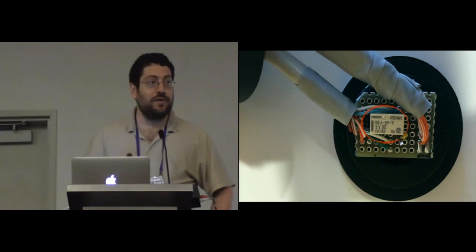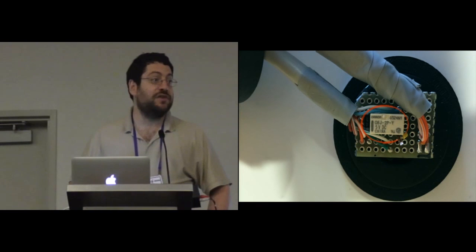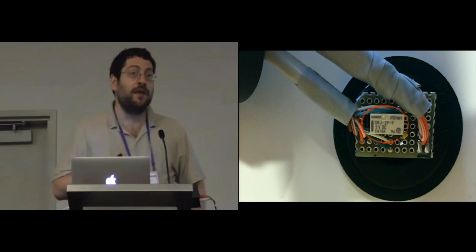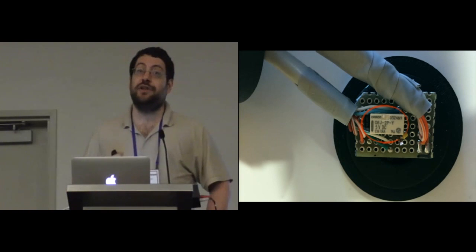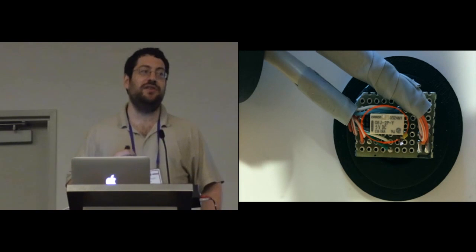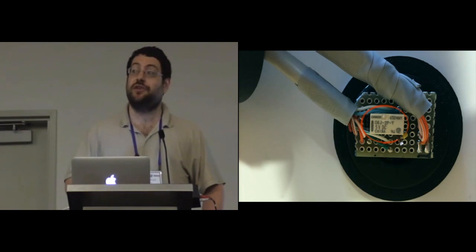Now, a relay is slower than a solid-state switch by orders of magnitude. It takes milliseconds to turn on rather than nanoseconds. But that's fine because we use a double pole relay, which means we get a signal back from the relay when it's actually closed. So we know the exact instant where the touch really occurs, and we use that for our timing.